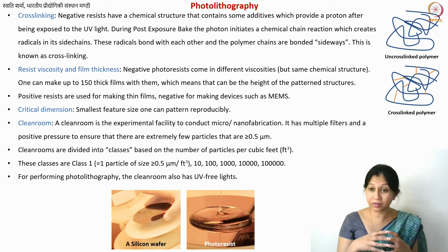Class 100 is used, but only in very sophisticated industrial facilities. Some research institutes do have it; in fact, we have a class 100 clean room here at IIT Mandi, but it is used only for extremely important applications when we are dealing with very, very small feature sizes, and not for general photolithography learning purposes, for example.